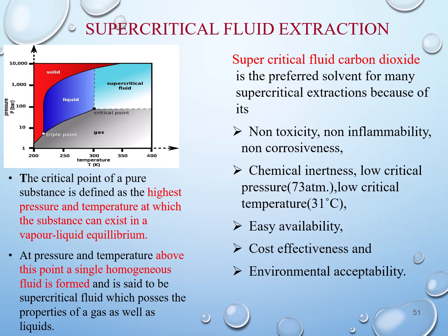So degradation is also avoided. Then it is easily available, cost effective, and it has environmental acceptability. That is why we are using supercritical fluid carbon dioxide for extraction of volatile oil in supercritical fluid carbon dioxide extraction.